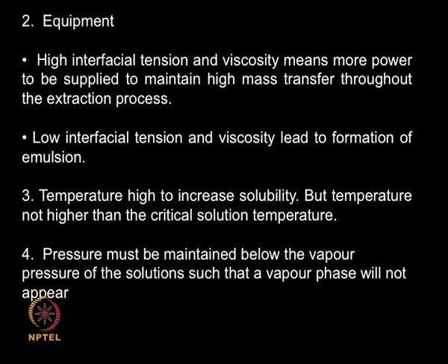This happens if you are using a very low boiling solvent. If I am using say pentane, or a very low boiling hydrocarbon, you may have the hydrocarbon both in the liquid and the vapor phase. So, some of the hydrocarbon will be lost, and you also have to think about flammability issues. So, pressure is very important if you are dealing with low boiling solvents.